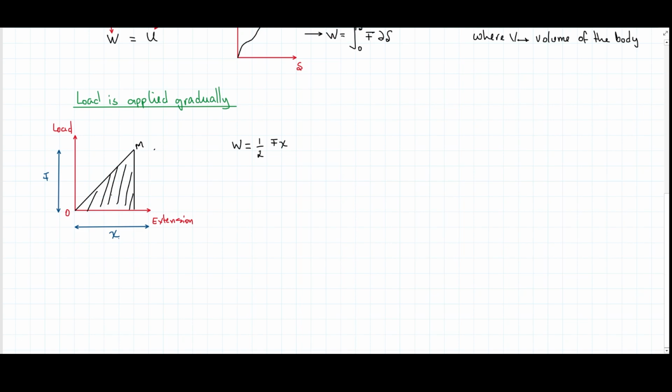For example, we like to put it in terms of the volume, because we have talked about modulus of resilience. Let's put it in terms of stress, because at some point for us it's more interesting to see how much stress is developed instead of forces, because stress is the one parameter that is going to allow me to compare to something else in terms of rupture, for example, or plastic deformation. And also stress is going to tell me what is the proof resilience of this case, or how to calculate it, because proof resilience, remember, is the maximum strain energy you can store in the body. Well, basically it is when you stress the body up to the elastic limit. So let's work it out so we can define strain energy in terms of those other terms.